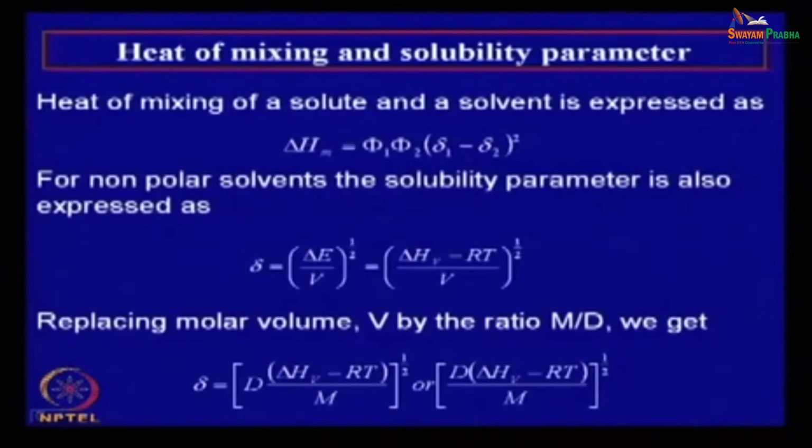If the energy supplied to the solvent crosses beyond the intermolecular forces of interaction, then only it starts vaporization, start boiling, vapor formation. So, it is very much related to the heat of vaporization, which is related to the cohesive energy density, and I told you what is cohesive energy density earlier.